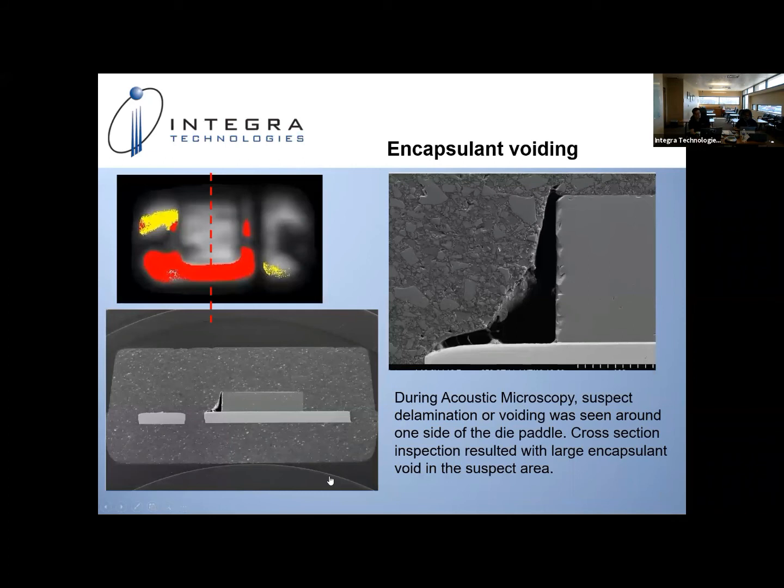Question. Sure. Couldn't some of these defects be detected at post-bond visual inspection? So post-bond visual, he's talking about when the manufacturers do the bonding, there's a visual inspection there. Not visually, but if they had done a 100% X-ray screen of that lot, they would have caught it.